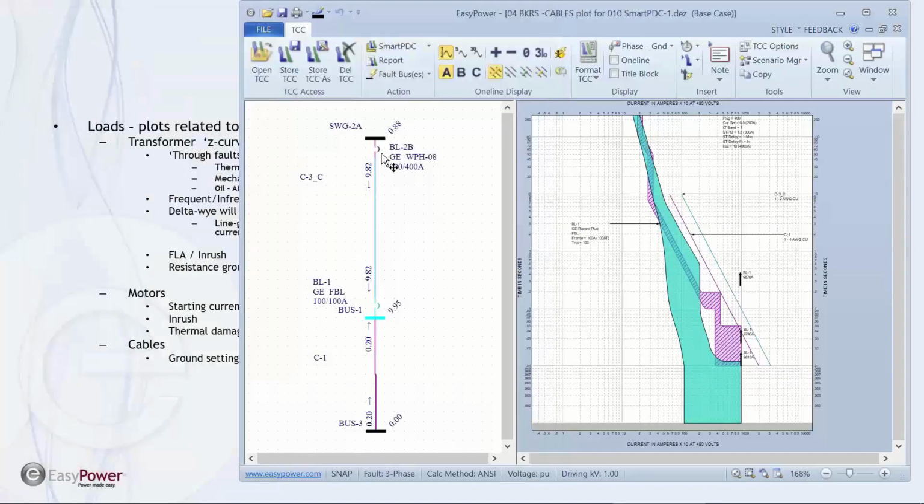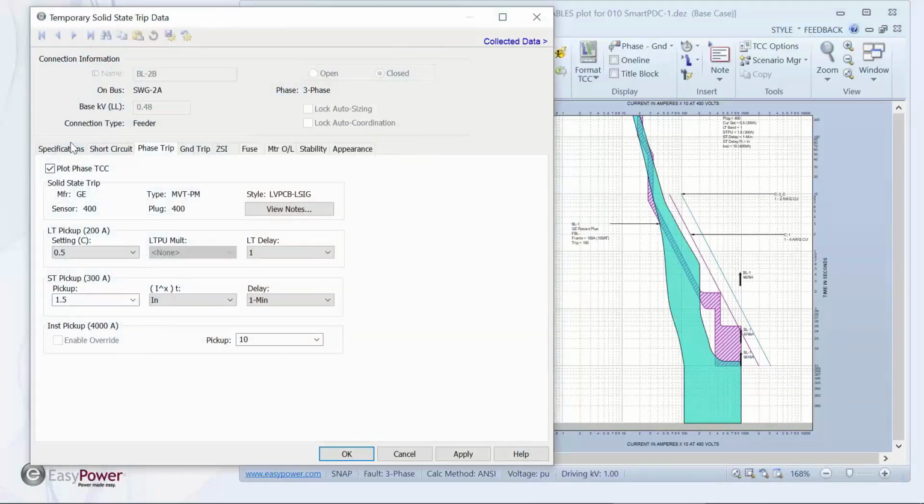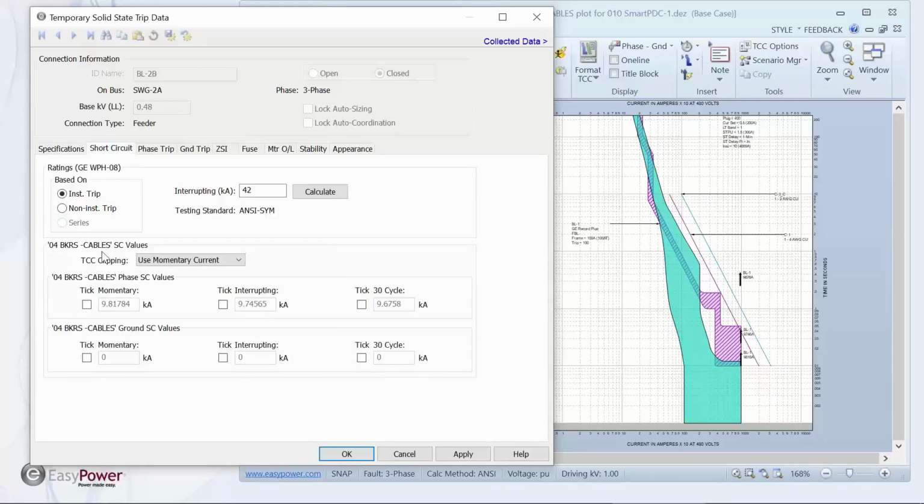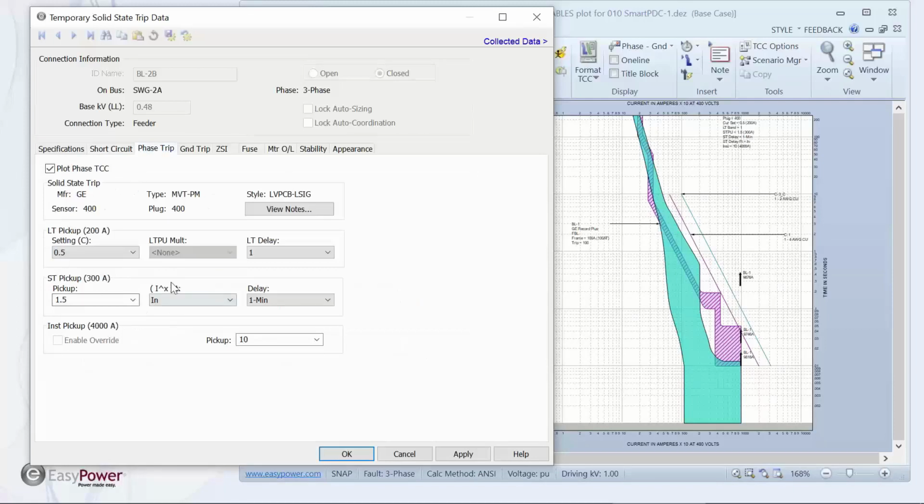Likewise, on a low voltage power circuit breaker, which has a trip unit, there's a setting for the manufacturer's trip unit, and we're seeing that this is set up for long-term, short-term, instantaneous, and then ground selections. And so we can go into our set points, and based upon these settings, we set up the long-term pickup.